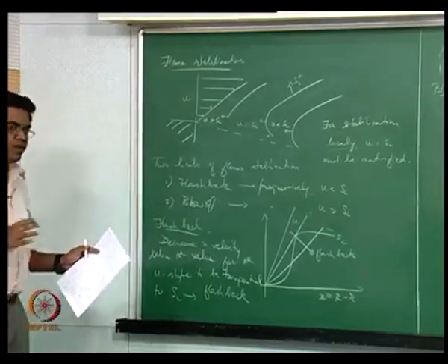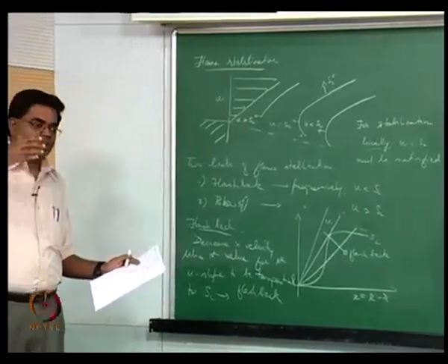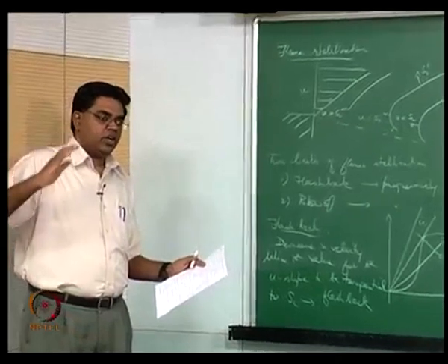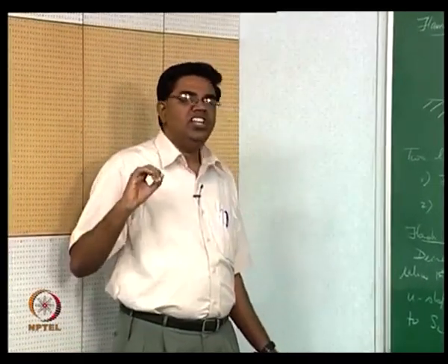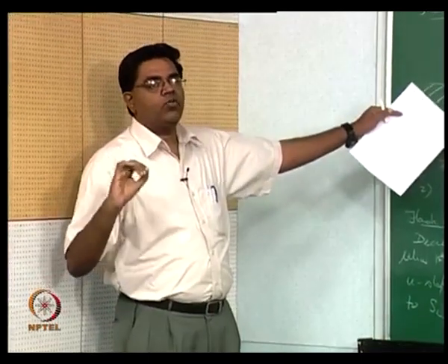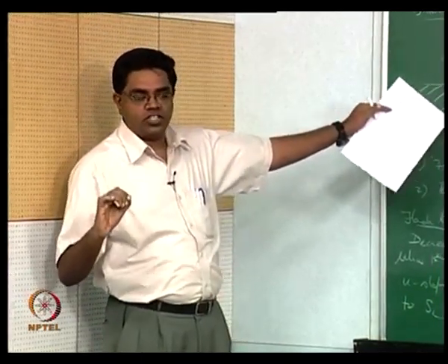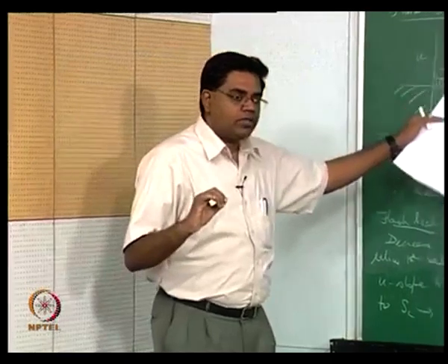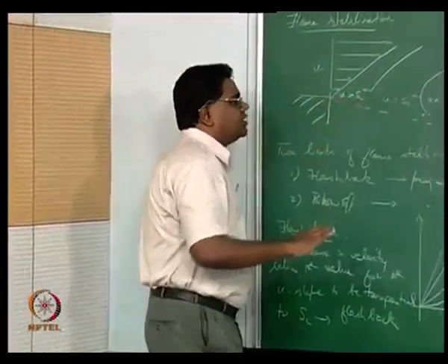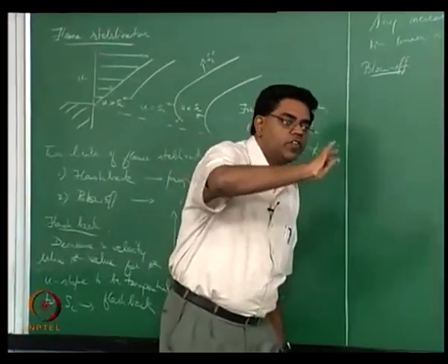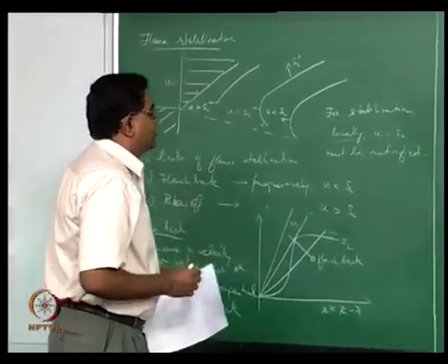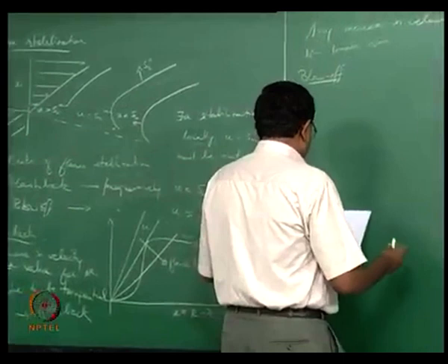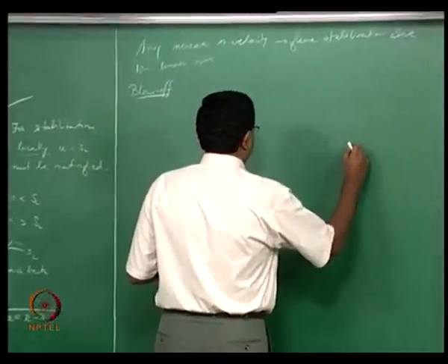So for a fairly wide range of u's given a certain SL, you can have a flame that is held pretty much near the rim without worrying about the details of how it is attached to the rim. If you have to worry about it, then you start seeing that the edge of the flame starts moving away from the rim a little bit, and progressively. So how does it really adjust?